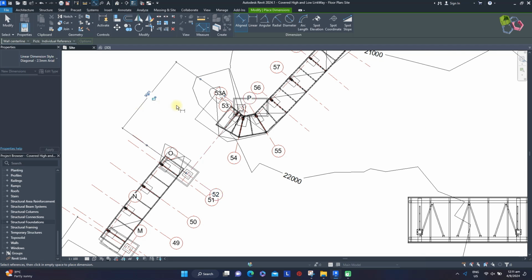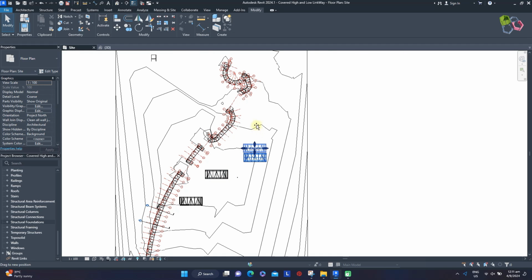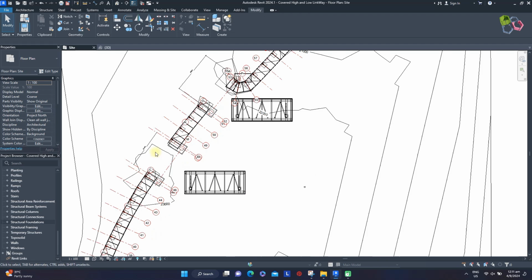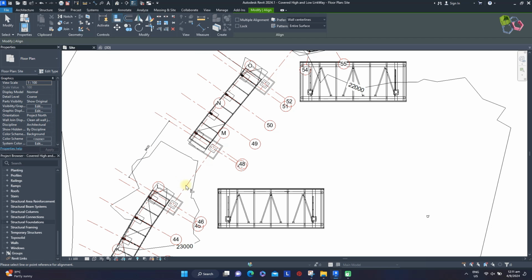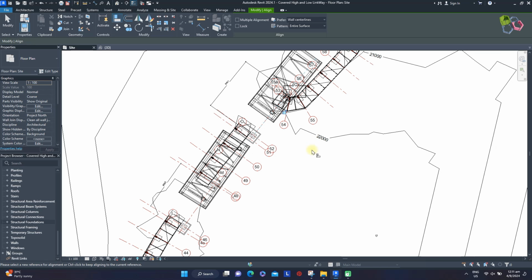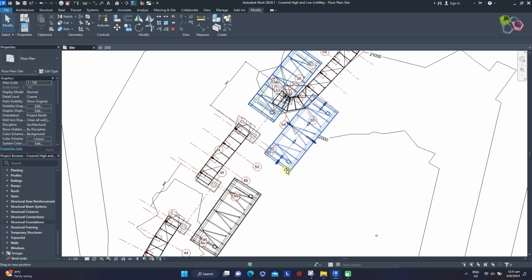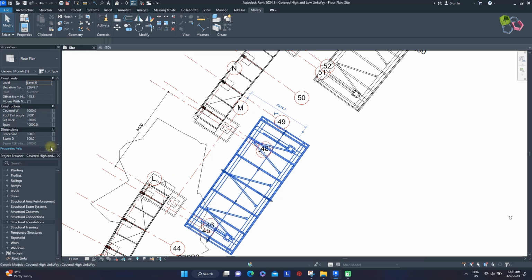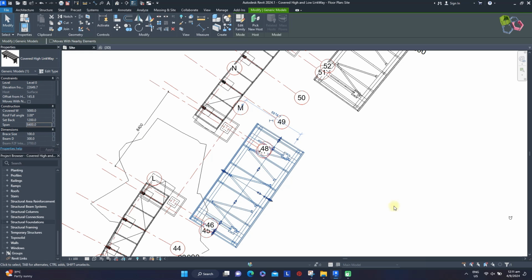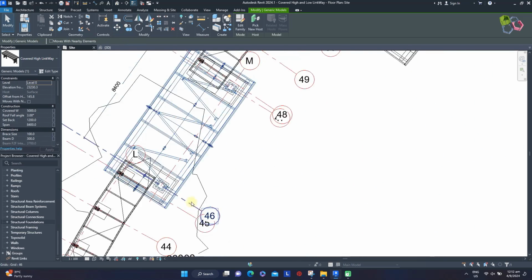Second high Linkway span will be 8400 mm. Third high Linkway will be 9000 for span, and move the family back to the second high Linkway location. Here for align second high Linkway with span direction. MB for move from here to here. Here for align, MB for move. In the property panel, input 8400 mm for span. MB for move with this column base point to high Linkway footing center.